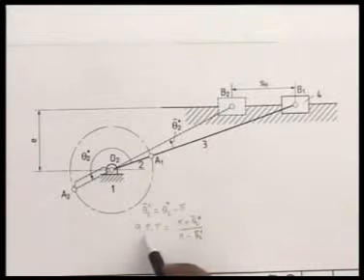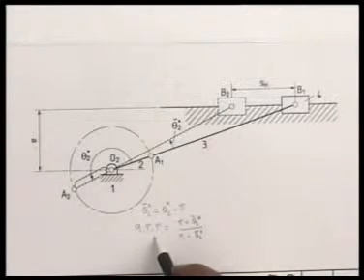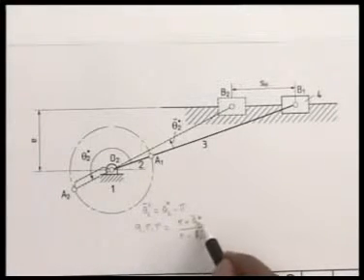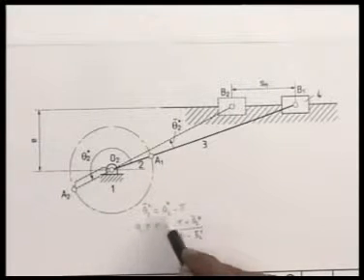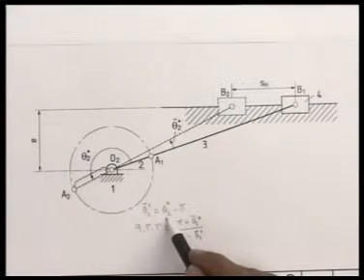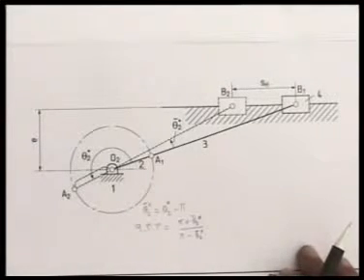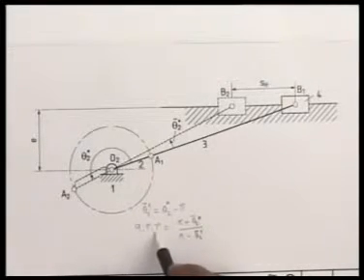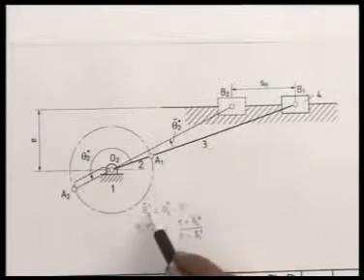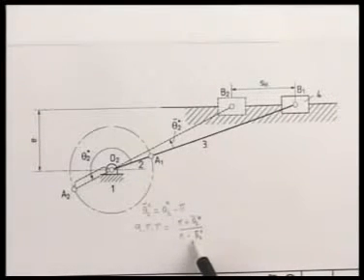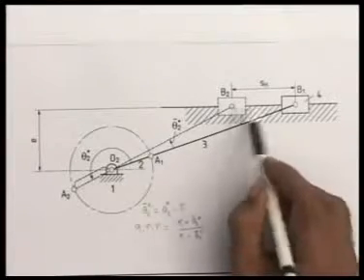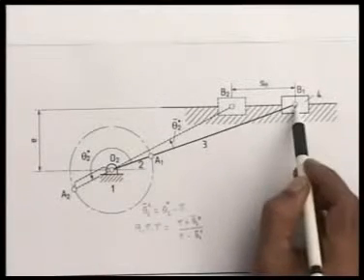So, if the desired quick return ratio is given, then we can obtain theta 2 star bar, and from there I can obtain theta 2 star. To solve this problem geometrically, what we should notice is that for a given quick return ratio, this angle theta 2 star bar is fixed, which you can solve from this equation, and this is the stroke length SH.